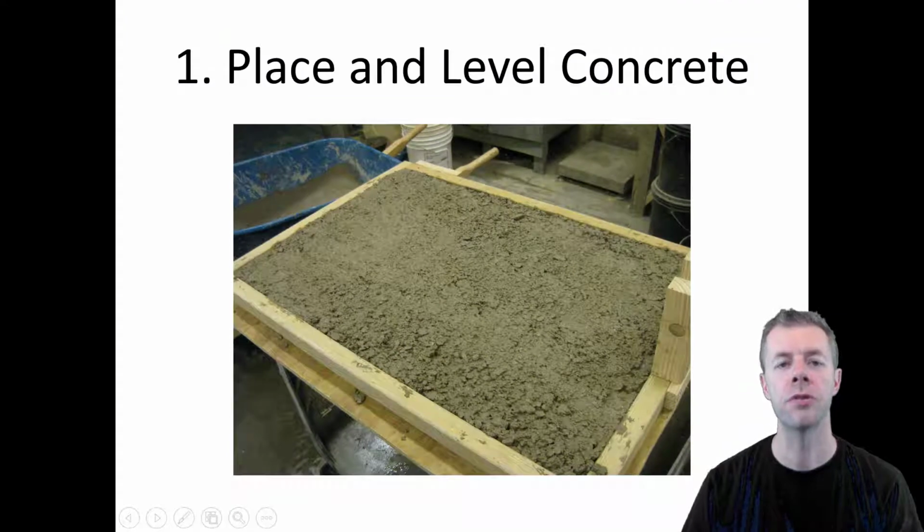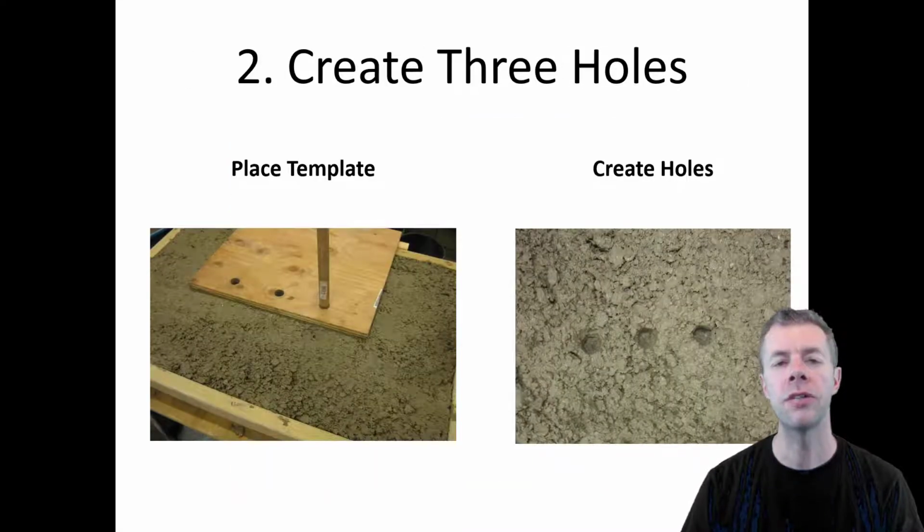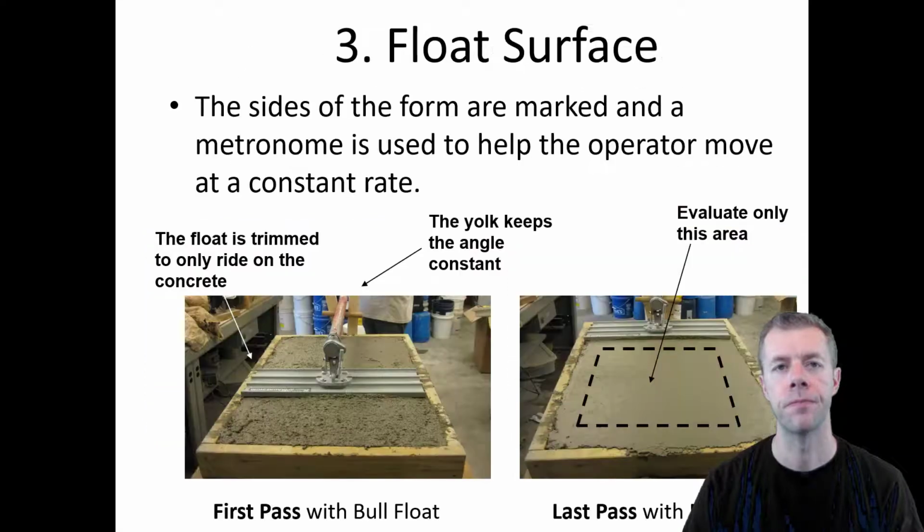There it is in the forms. Strike it off the top. Place and level the concrete. Now we're going to use a template. We're going to place 3 1 inch diameter and 1 inch deep holes in the concrete itself.